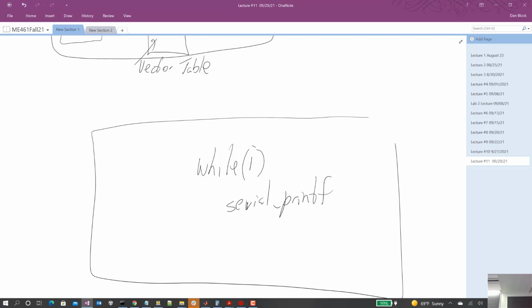So the interrupt function is called, the first thing it does is it saves the context of the processor to the stack. Okay? Then it actually runs your code. So by putting underscore interrupt as the type of your function, the C compiler does this automatically for you. Okay? So the while loop was halted, but we've saved the state of the while loop code in RAM, in stack. Okay, then our code can start running, march through it, right?